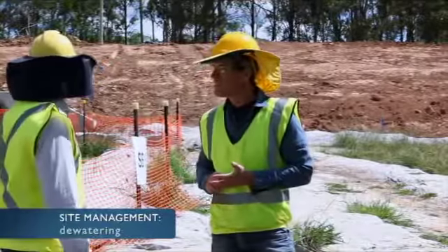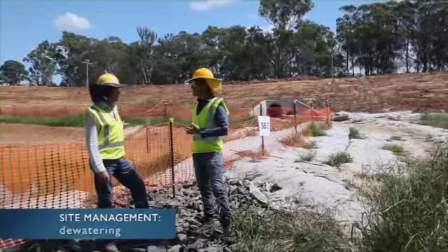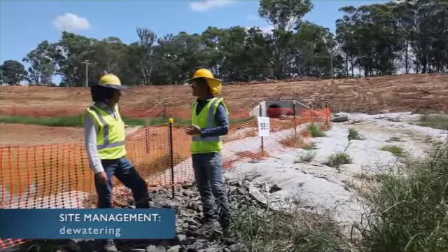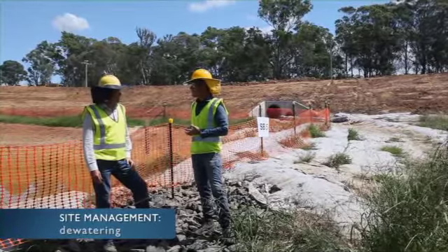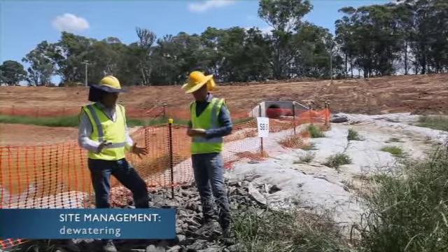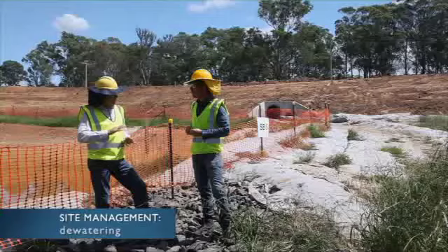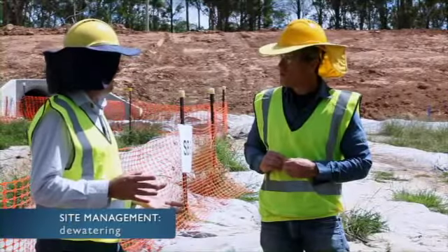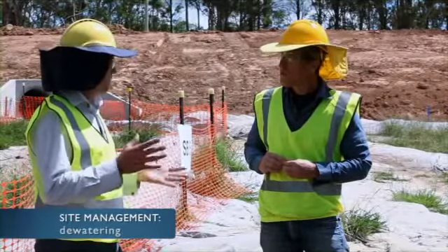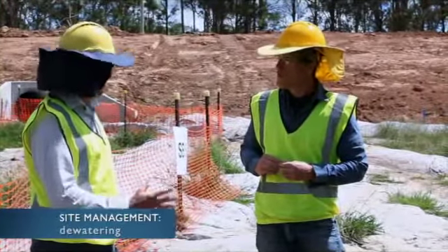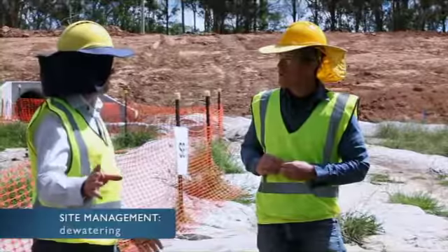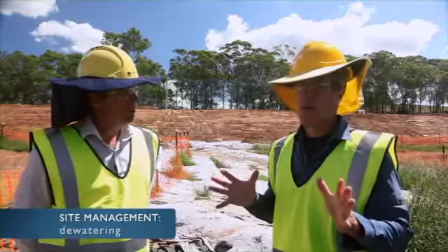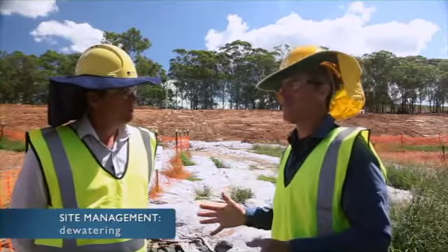Sure, Pete. Well, dewatering is essentially removal of ponded water either from sedimentation basins or from other areas of the construction site. Why it's such a big risk is it's a controlled activity, so it obviously follows on from a storm event and it uses techniques such as pumps. And the main danger there is that your pump may drop and fall into the sediment and pump that sediment into the receiving environment. So, Chris, no unattended pumps spewing sludge into the environment?